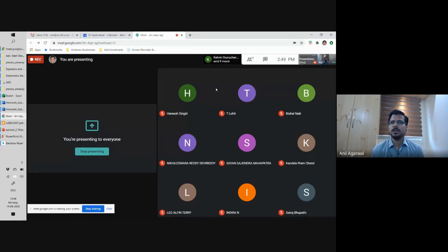Fine. However, in the service limit state, if that is exceeded, and I'm not saying exceeded by 100 times, exceeded beyond what is mentioned, okay, once you remove the loads, the structure will be perfectly usable. Okay, only at that time it will not be able to serve your requirement of the service conditions, right?